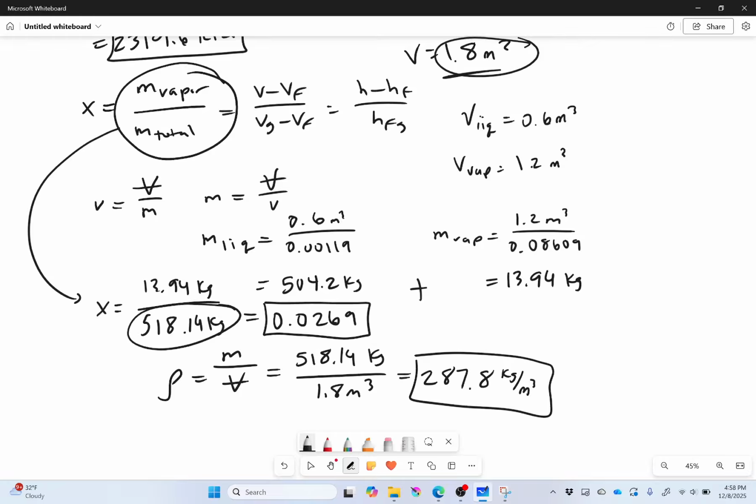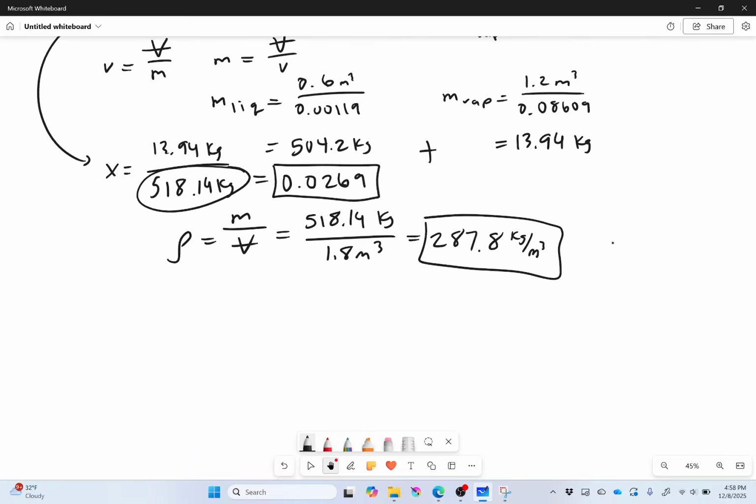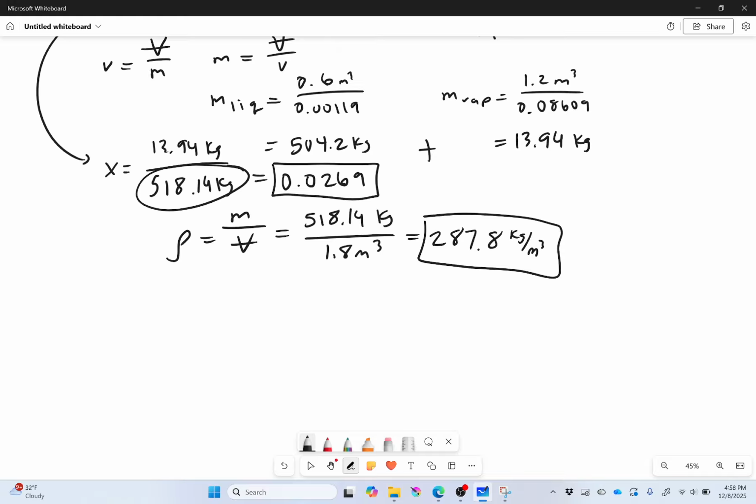Or we can do it the slightly harder way. Why am I showing you the slightly harder way? Because a lot of times you're going to have to use this. If you have a saturated mixture, that means that I have part liquid and part vapor. Then my properties are a mixture of the vapor properties, the g properties, and the liquid properties, the f properties. It's somewhere in between those. Those are my boundaries, with liquid being on the lower end and vapor being on the higher end.